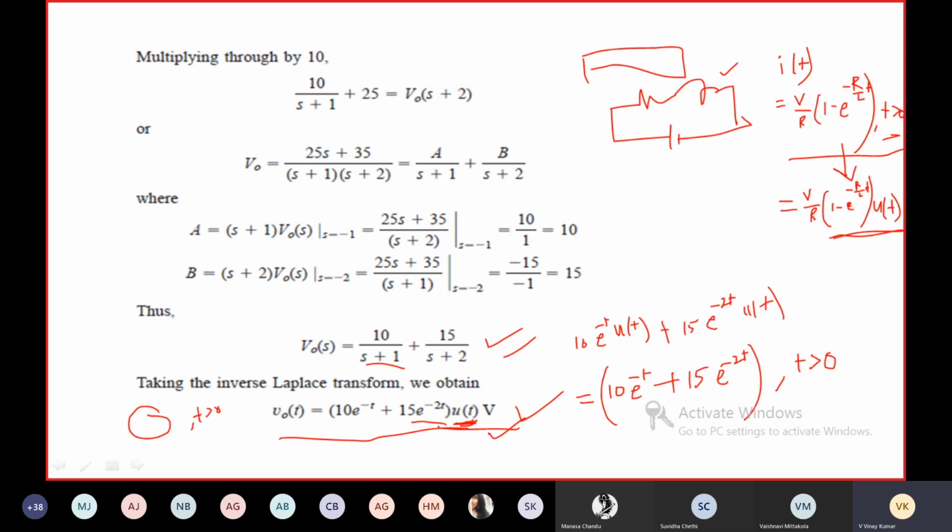First you take the given circuit and redraw it in S domain as it is given in time domain. You use any network technique, KCL, KVL, source transformation, superposition theorem, or any network reduction technique, and solve. Finally, you use inverse Laplace transform to get the required equation in time domain.